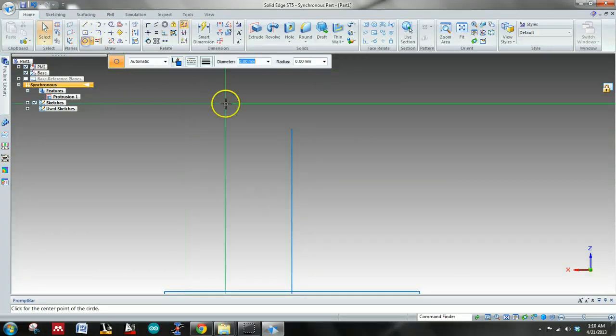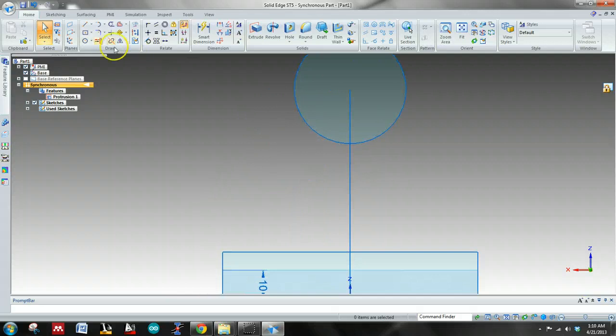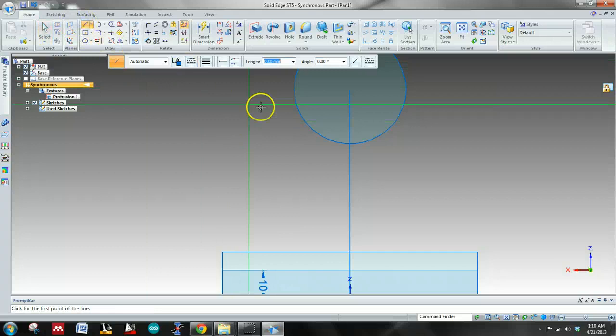And we're just going to put this on the outside, which is 36. Now, to make that really interesting thing that we had before, we need to come tangent to this. Since it's half, it's 18. Okay, so I placed it there. So these lines are just to, I'm sorry, Shift Tab will get you back to the length, 36 over 0.